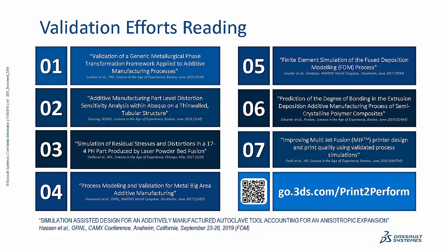Sorry, I don't have a slide for it, but in this case, the mold is made out of polymeric materials. After they predicted the deformed shape through the simulation based on the major thermal expansion coefficients, they did the shape compensation on the original design. So they were able to 3D print the reconstructed design and get the autoclave composite mold as initially designed.